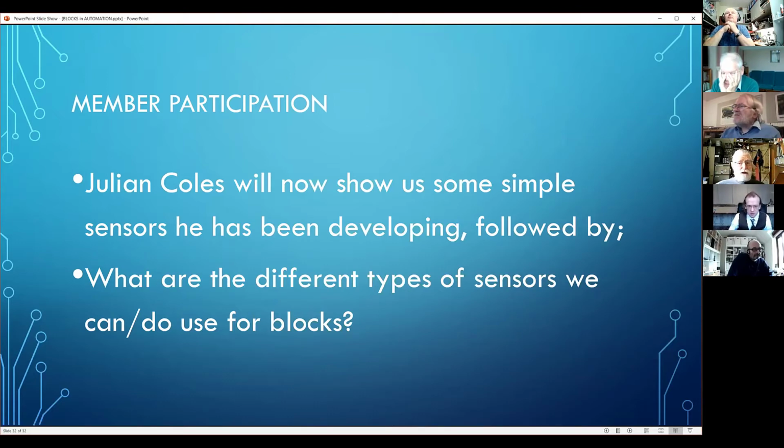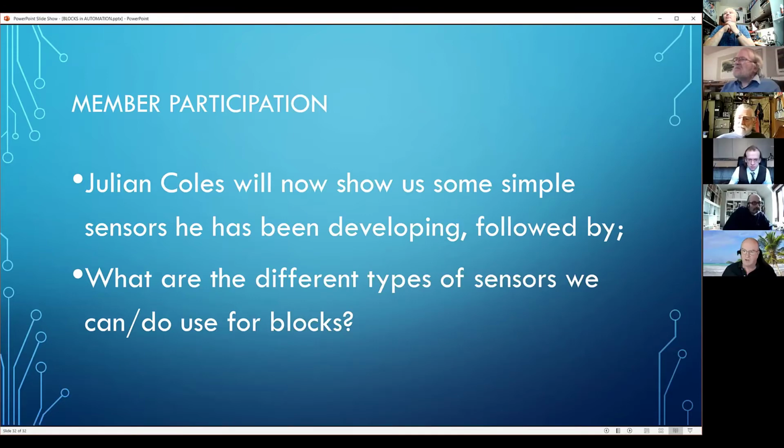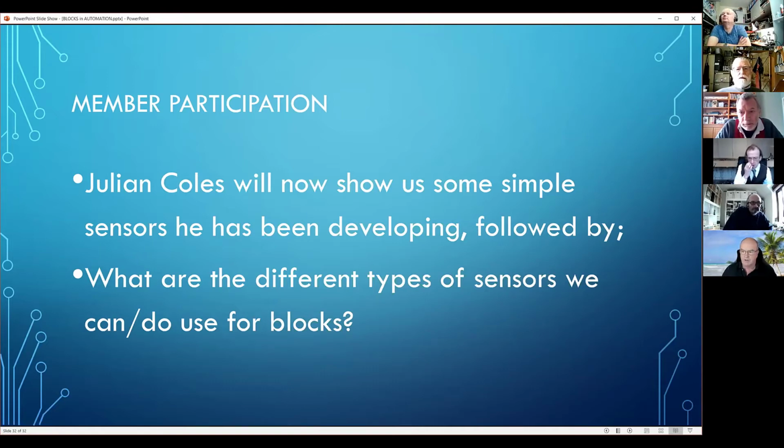I should be using JMRI. So okay, I take your point about the ROCOM and those particular ones. But in JMRI, you have to include the turnouts if you're doing any sort of automation, otherwise it simply won't work. Yep, that's a very good point, actually. Definitely to be included in JMRI, otherwise, as I say, it won't work. With the special signals, it will really confuse it if you don't include the turnouts in all the blocks. The blocks have to be connected together for the system to know where the train is and to pass the information on to the next block. Yep, that's right. Okay, thank you. That's very useful.